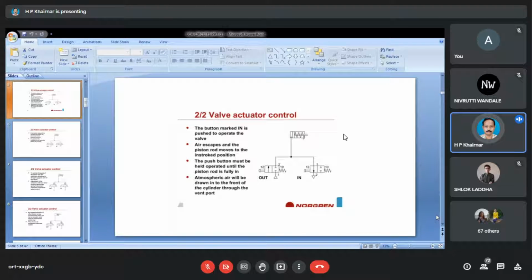So you need to keep checking it all the time, and you need to regulate that pressure. If unknowingly it moves beyond 8 bar, then anything can happen over there. So for such things, you need valves which can regulate the pressure. You need valves like pressure relief valves. If the pressure exceeds in a particular valve, it can be released. So all such valves, if you add them to the present circuit, will only improve its functioning.